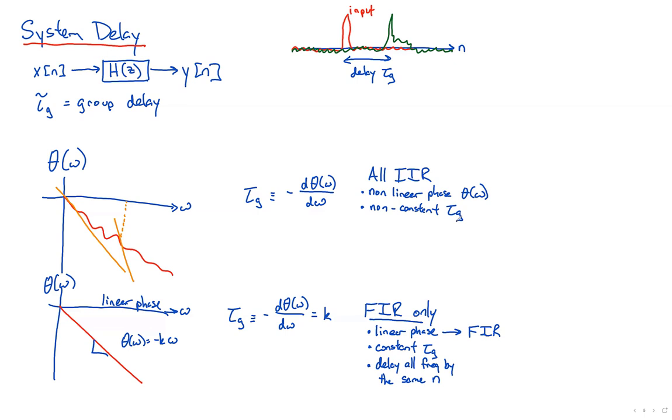The group delay is a function of frequency, and the amount of group delay depends upon how much frequency you have. It might move low frequencies more and high frequencies less in the time domain. And that means that since they delay different frequencies different amounts, these must necessarily change the shape of signals, versus the FIR filters that, if they're linear phase, do not change signal shape.